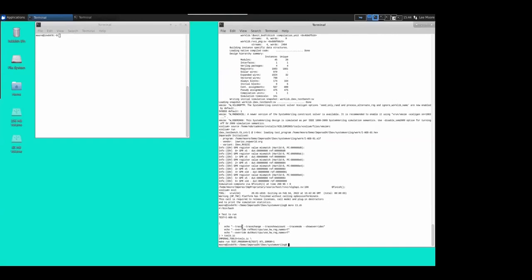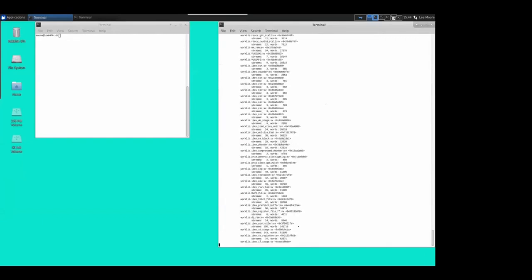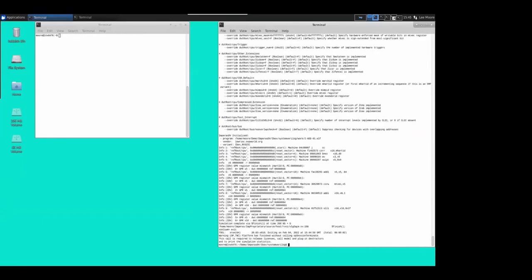So we're telling it to do some additional tracing, trace changed registers, give us an instruction count, and tell us about modes if it's switching. It just so happens in this one it only runs in machine mode, but if we had a more complex core, then it would tell us about mode switches as well. So let's run this again. It's still got the RTL fault in there. We're going to execute and see what additional tracing we get out.